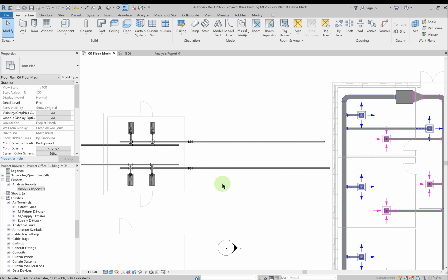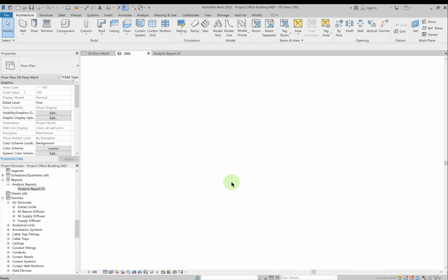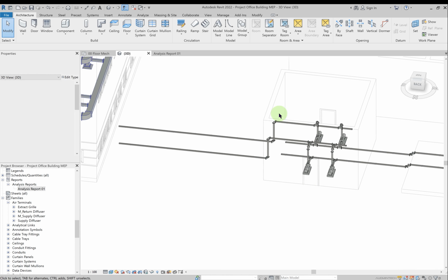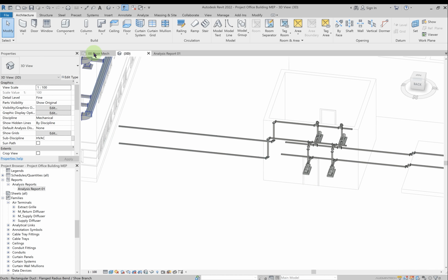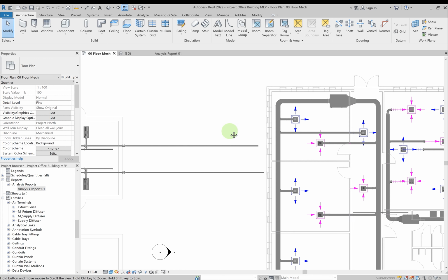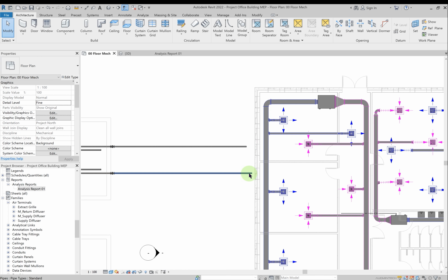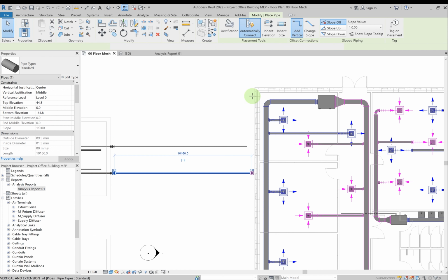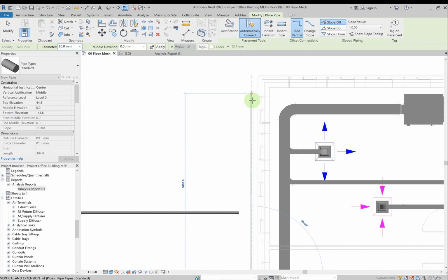So that is also one way in which you can do the designing. I've selected this method. Now over here you can see the new fittings that have been brought into the system. So this is the pipe that we have afterwards. Okay, now what we can do, we have to continue creating this. So select this one, right click, draw pipe, and we can go till here.